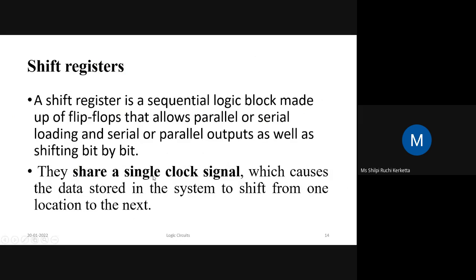So we will start with shift registers. So I started it yesterday. A shift register is a sequential logic block made up of flip-flops that allow parallel or serial loading and serial or parallel output, as well as shifting bit by bit. So actually it is used for shifting.